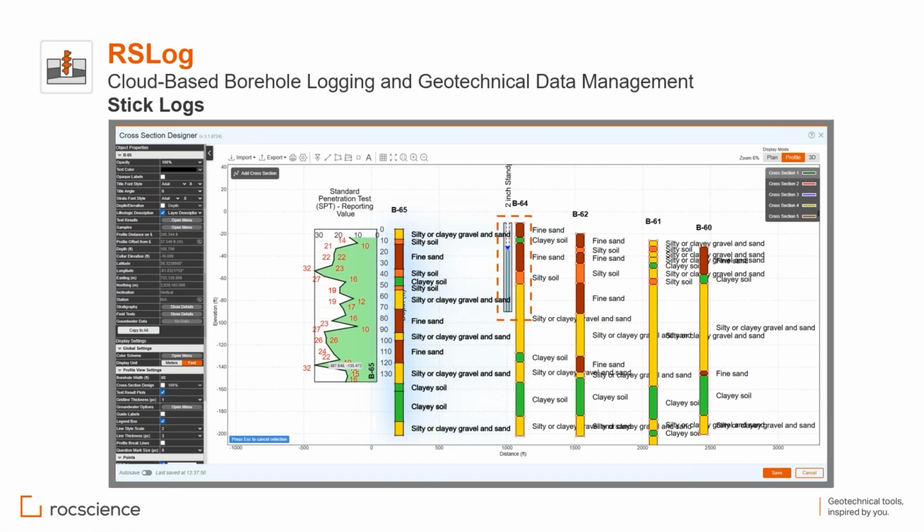Again, we are going to add nested piezometer in the next few weeks if you have multiple piezometers in a borehole. And now in this example, you see a graph of SPT data for this borehole. You can add up to 2 different graphs to each borehole. Both of them could be field tests, or both of them could be lab tests, or you can combine. Let's say you want to have SPT on the left and you want to show moisture content, or pocket penetrometer on the right side of the borehole.